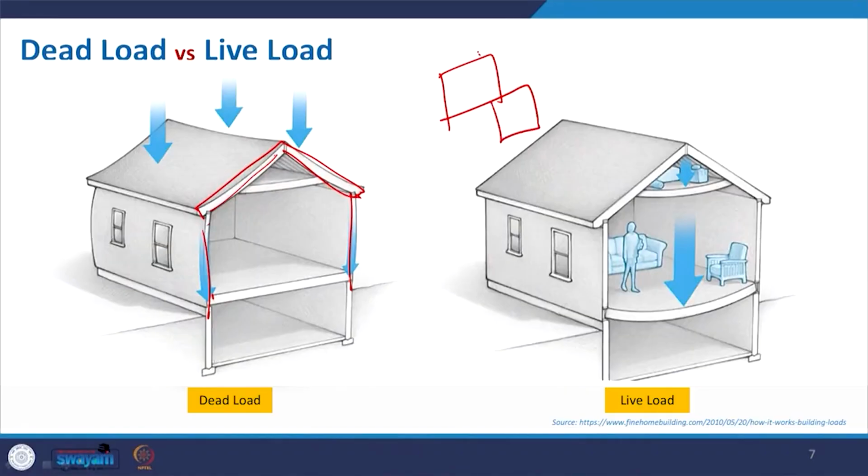When we design a building based on the requirement, we make the space division and create those beautiful spaces, and then in order to bring it to reality, we have to design the structure. At that moment we have to take all this dead load and live load. So, for a kitchen it will be something different, because in a kitchen along with normal furniture, there will be some permanent furniture. When it is built permanently, even though it is in the furniture category, it will be considered as dead load, not live load. So, that we need to understand.